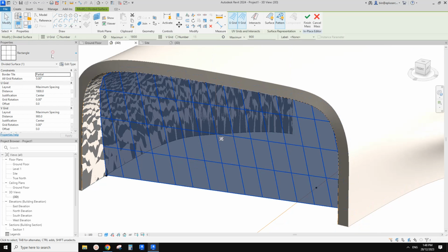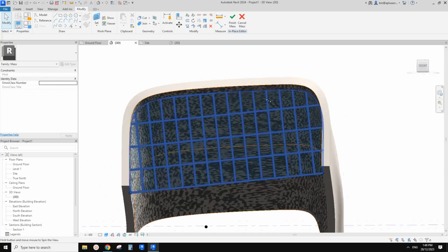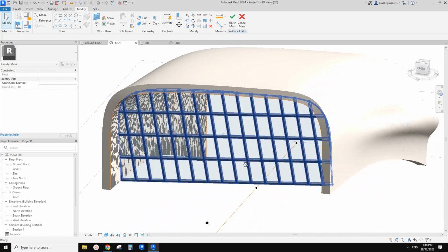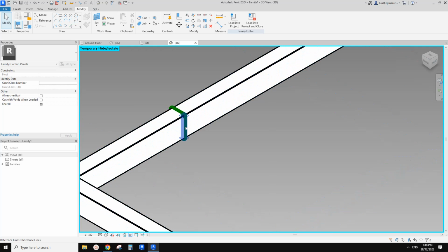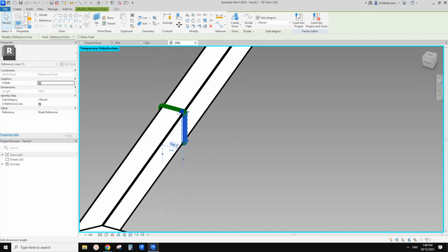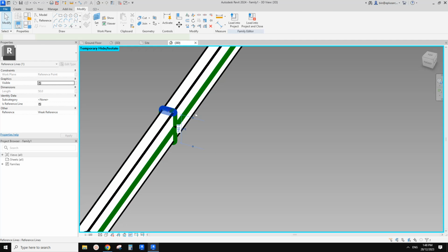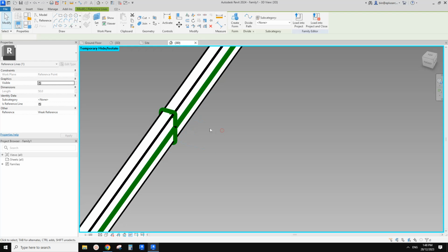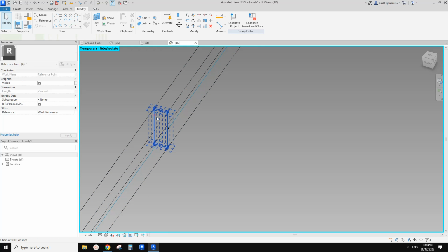And then we can use that pattern-based family we just made. Oh, these are huge. But anyway, this is how we can do it, right? That's actually 150. Let's use 50 by 150, and also I'll use TL and WF, and maybe I'll center this.